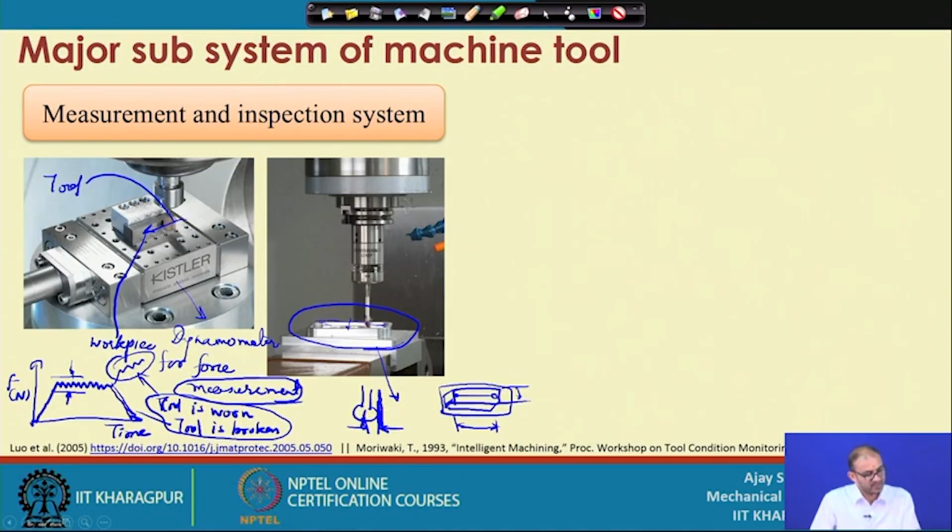So, this is inbuilt inside that probe, but you should also know where the measurement is being taken. So, it measures in this direction. It records this dimension, then goes to the center of this, then does the measurement in this direction. Or suppose you want to see the different things at this location, then you can take more than one reading lengthwise and widthwise also. So, you can get one extra piece of information: whether you have a perfectly square component or a rectangular component.